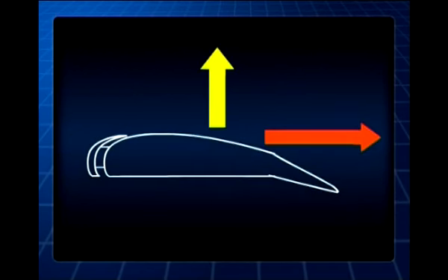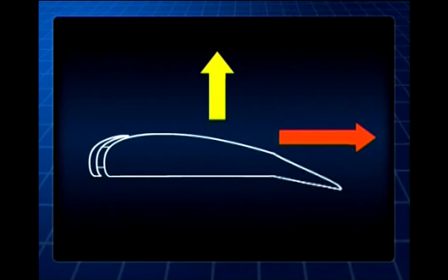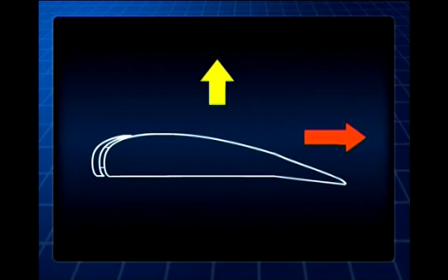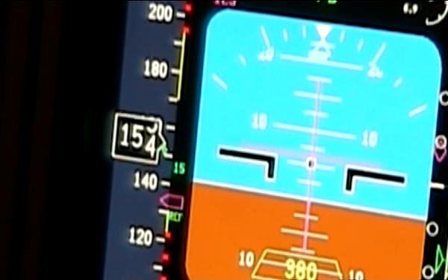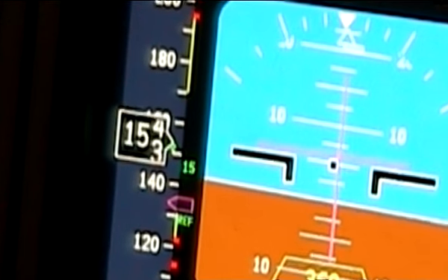Fully deployed flaps not only generate more lift, but they also cause more drag, slowing down the aircraft, and now there is less engine power available than in a normal situation. But there is a price to pay for landing with flaps 15, a somewhat higher final approach speed than when landing with flaps 30 or 40.